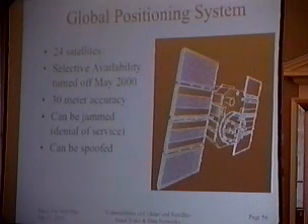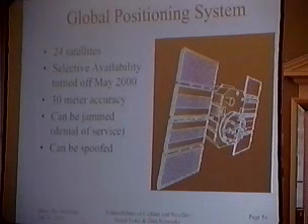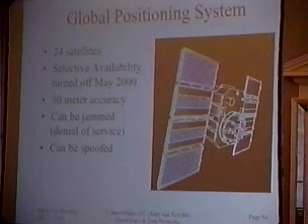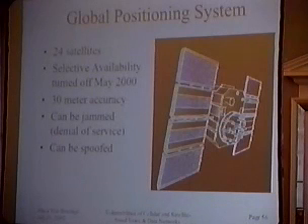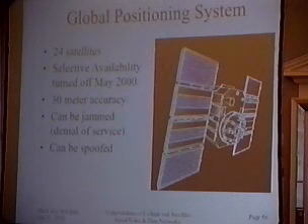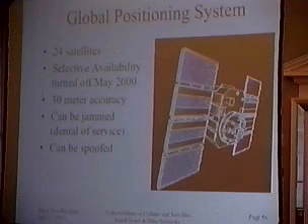GPS, I'll just go through this briefly. This, again, is a satellite system that most people can't talk to, but will listen to. The biggest thing about GPS in the last 2 years was that something called selective availability was turned off. It used to be that the government deliberately degraded the signal quality of GPS so that you couldn't get as accurate a position as you can now.